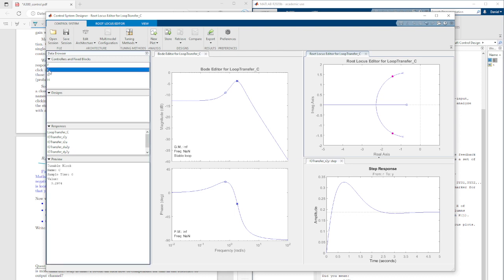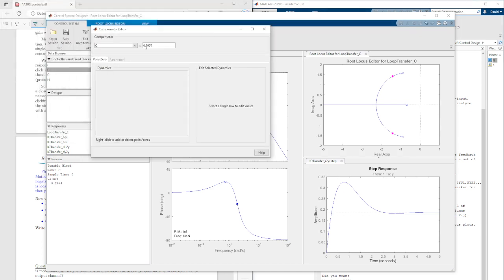So you simply double click here and you see the value, or it also opens up here, and the value is roughly 0.27. So technically you could also simply say 0.3 here, and Matlab will update the location here. See, it moved. Whatever you put in here, if you put in 2, it will again move and so on.